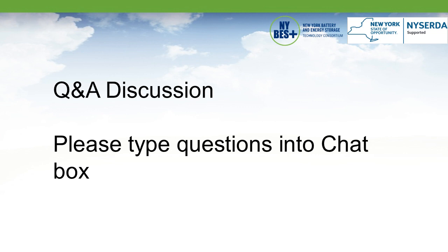This is Jason Bowsey. For multiple DG projects, that would constitute a single application, would be my understanding of it. There'd be a single application if two types of distributed generation systems were proposed. As we move forward with the inclusion of energy storage, a PV plus energy storage project is going to require separate applications: one for the energy storage and one for the other type of DG. But if it was two types of DG, the way I believe the utilities are doing it now, and I don't know if it's clearly outlined in the SIR itself, that would be one application.